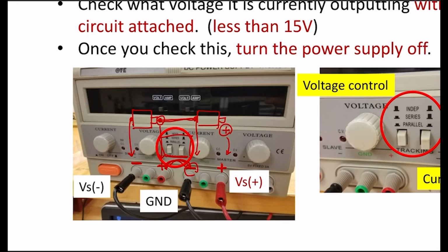so these 2 terminals are connected internally. So you can use either here or there as your reference or ground, because we are going to use this center as a ground or reference. And with respect to this point, this is going to be positive 15 volts, and with respect to here, this is going to be negative 15. Again, we don't have any negative voltages from the batteries, right? We just make it relatively negative. Okay, so that's important.